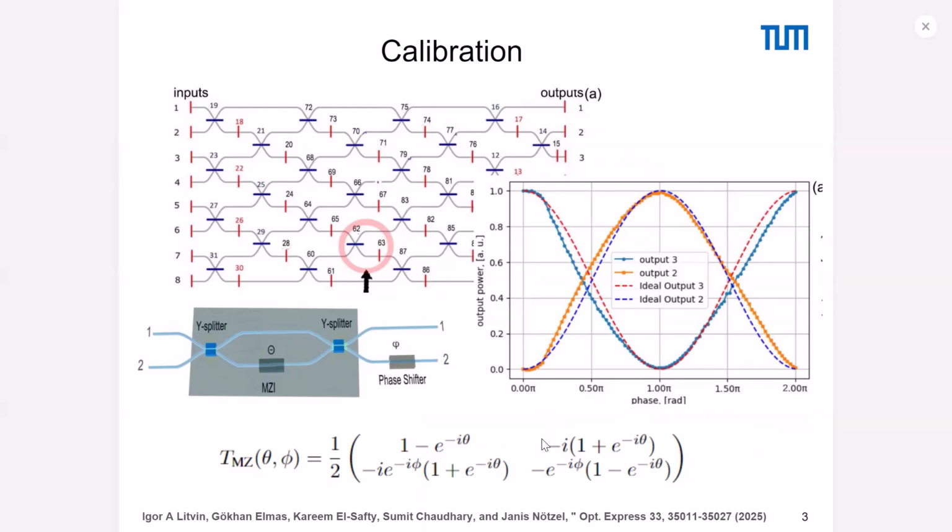And we can immediately see some interesting points. At 0, this is the MZI phase. When we have 0 phase shift, we have almost 0 error. It's quite okay, and then pi as well. These 2 points we call bar and cross points, and we can use the photonic processor almost with no problem there. The bar setting is when the MZI phase shifter is set to pi. If we have input 1, the output will also be 1, or input 2, output also 2.